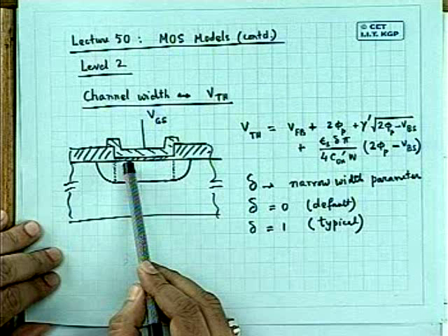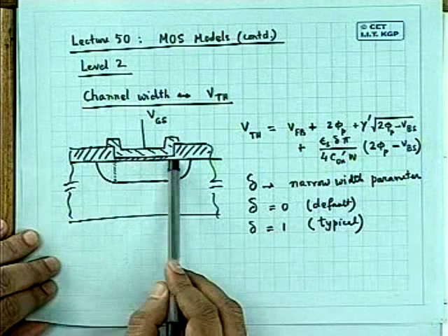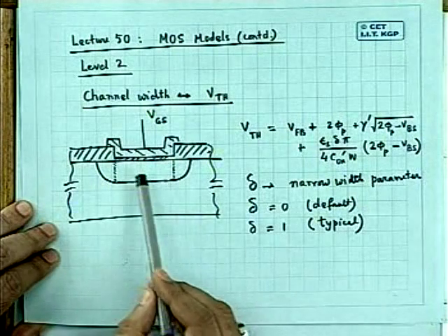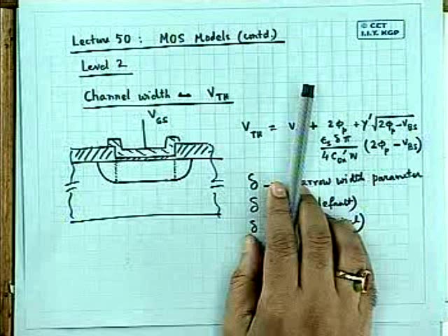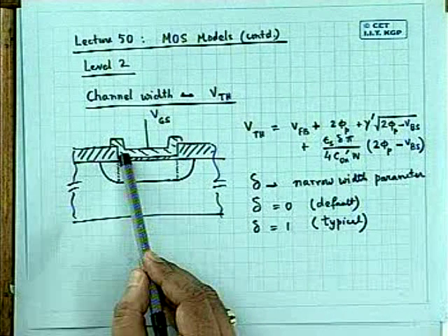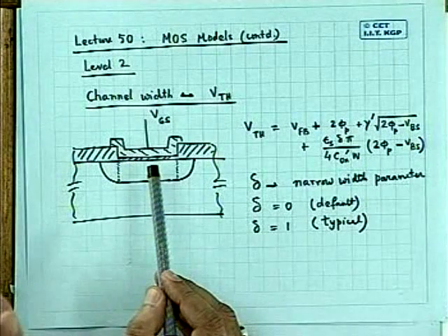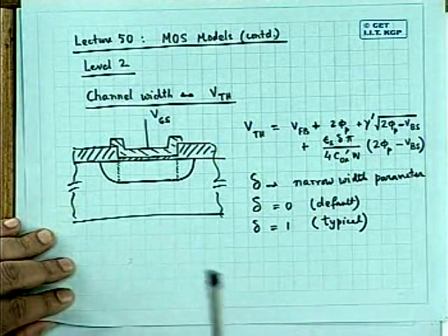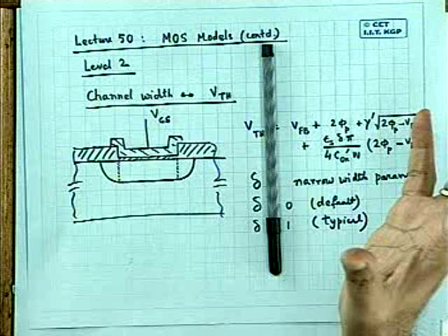Overlap because you know that firstly you see that so far as gate this side is concerned, you cannot align this thing exactly. There are two things happening. One is the fringing field effect. Secondly, the gate electrode is a separate lithography, isn't it? You cannot make the metal deposited exactly on this slot. You have to give some extra because of the mechanical alignment, okay? And that will give you some extra overlap. That is why it is called overlap. Actually, overlap means it is due to the fringe field plus overlap taken together. One is even if there was no overlap, there will be some extra things here. That is due to the fringing of field.